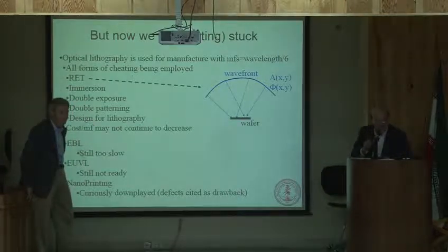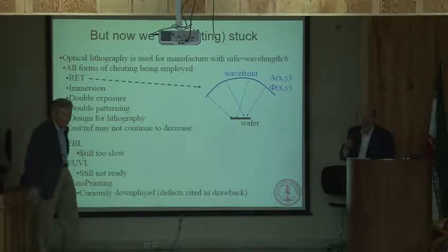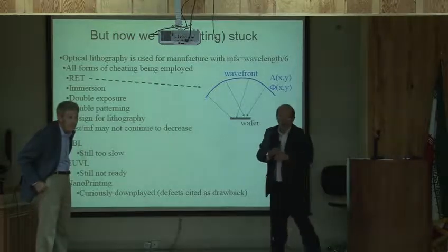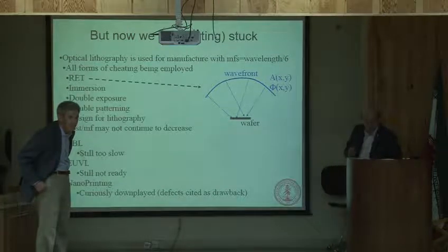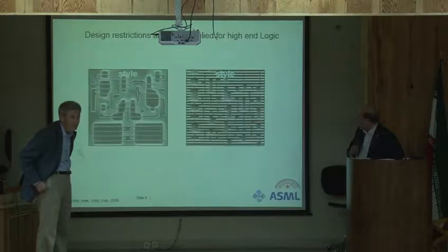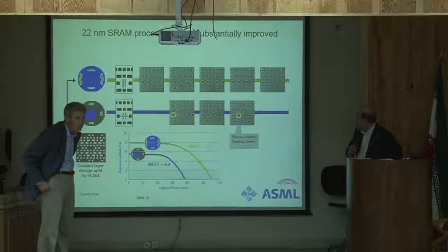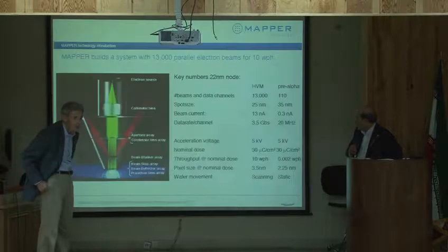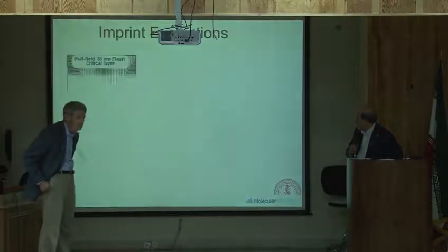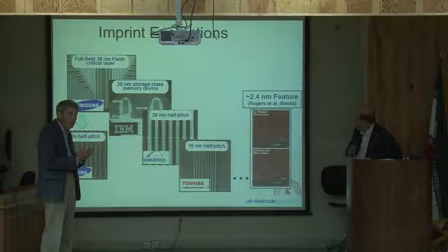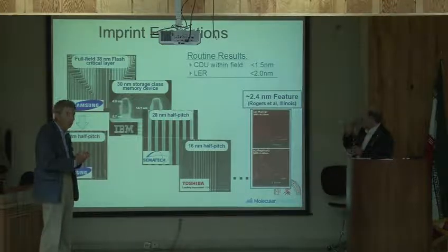Many thanks for your talk. I'm keen about the calculations for your conductances in the thermoconductance devices. You think of the layers, but in between the layers we have Kapitza boundary resistance or acoustic mismatch impedance. Isn't that the limiting factor in your devices? Normally, the reflection of the phonon impedance at the interface is much higher than... Yes, the interfaces are a problem.